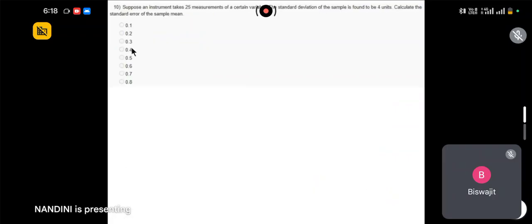Now, suppose an instrument takes 25 measurements of a certain variable. The standard deviation of the sample is found to be 4 units. Calculate the standard error of the sample mean. So we know the standard deviation is 4 units, and the number of measurements taken is 25.